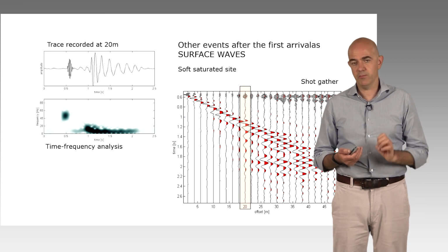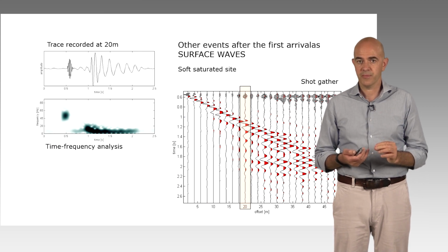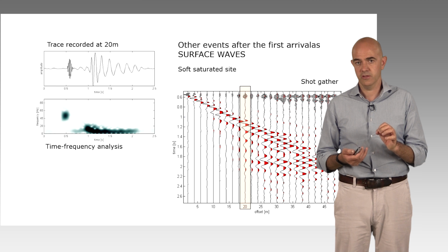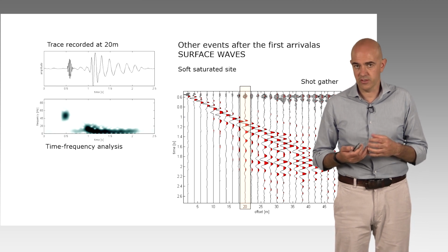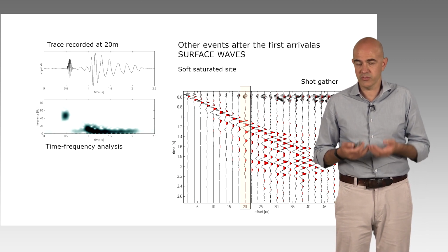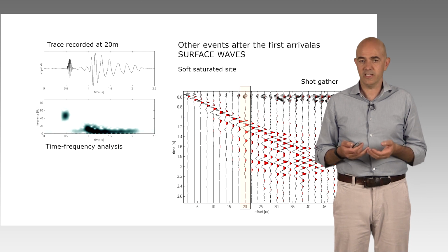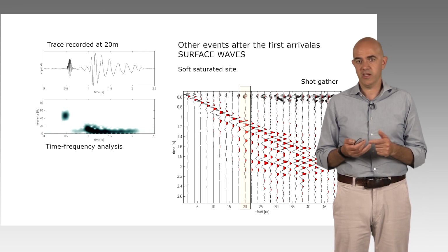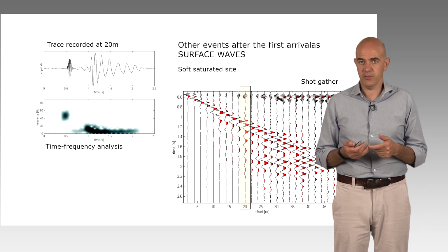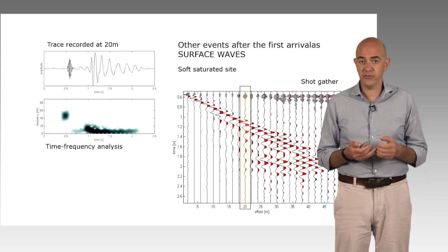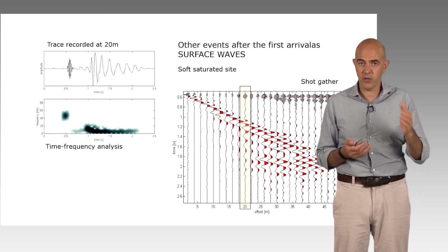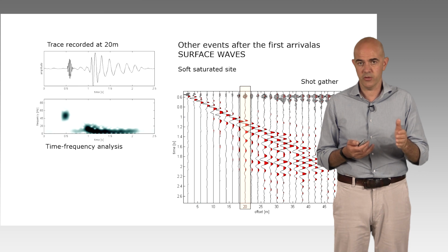And what is extremely important for the geotechnical characterization is the behavior of the solid skeleton. We are not really interested in knowing what happens if there is groundwater, because the failure of a site under static or dynamic actions is not happening because of compression failure. In most of the cases it will be shear failure. So the properties that we are interested in are the shear properties.